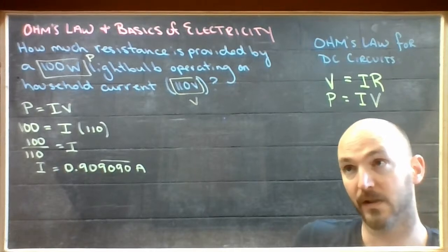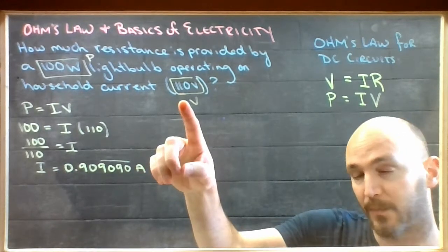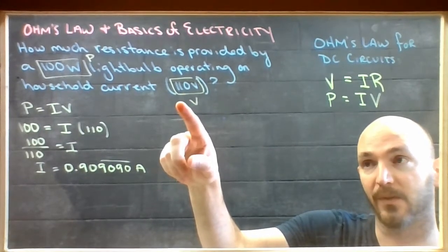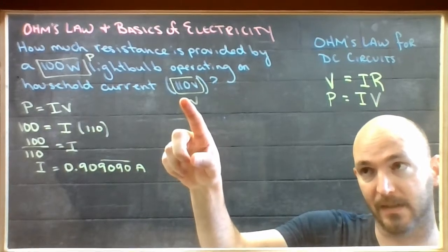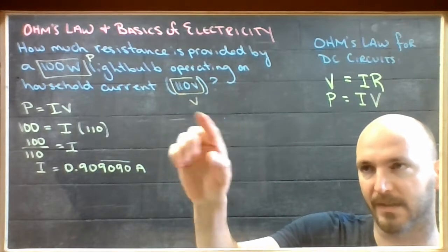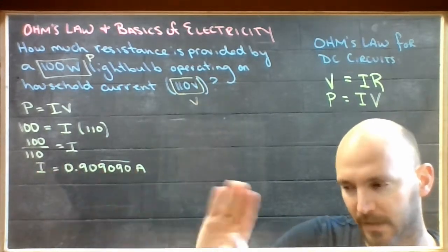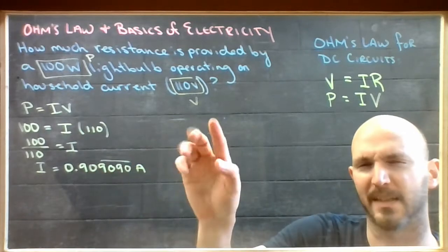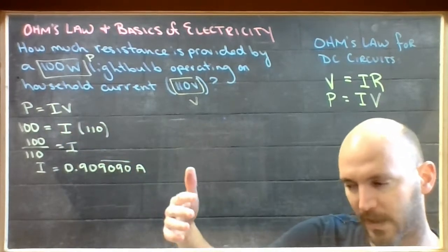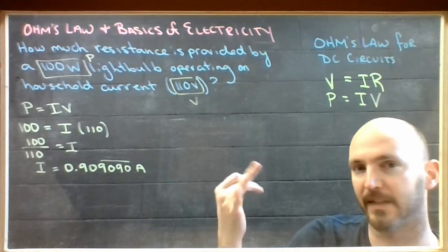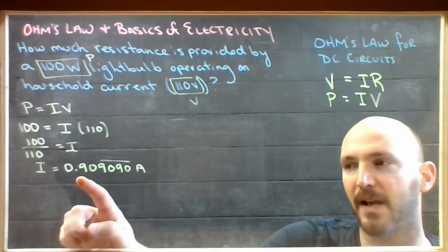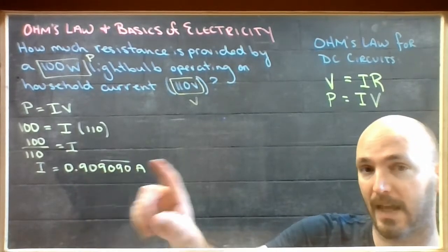Okay. So this process, whatever's happening between your power plant and your house, is delivering electricity that provides this kind of energy. We'll talk about that in a second. This is sort of the intensity of the electricity that's coming out. That's a good word, the intensity of it. In order to shed 100 joules per second of light and heat and whatever else is wasted in that light bulb, at this level of intensity, that bulb has to be receiving 0.9 amps worth of current.